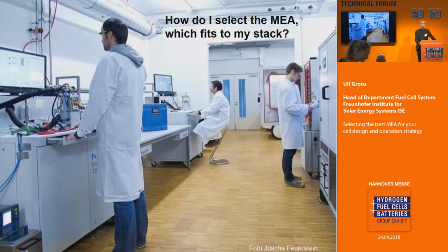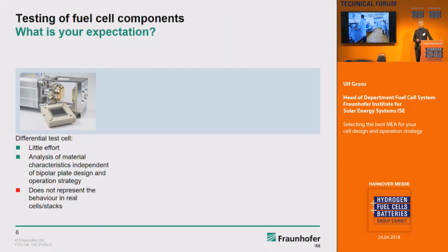So, the question for today and for my talk is, how do I select the MEA for my special cell design, my special stack design, and the operation strategy, the philosophy which I have in mind for the system operation. What we typically do today is work with differential cells for material selection and material analysis.